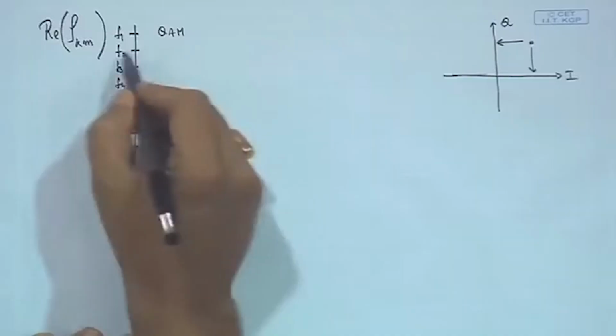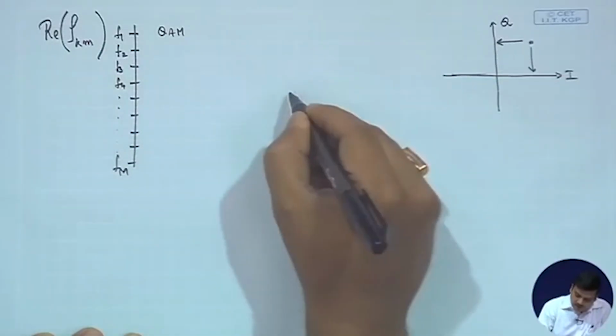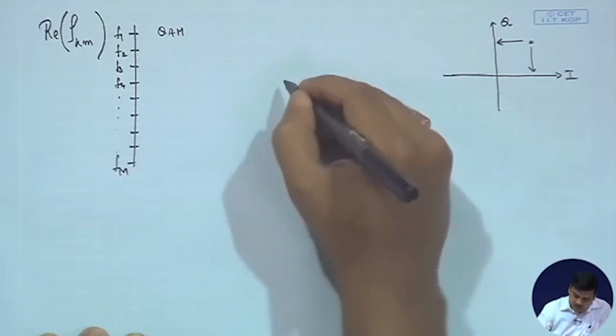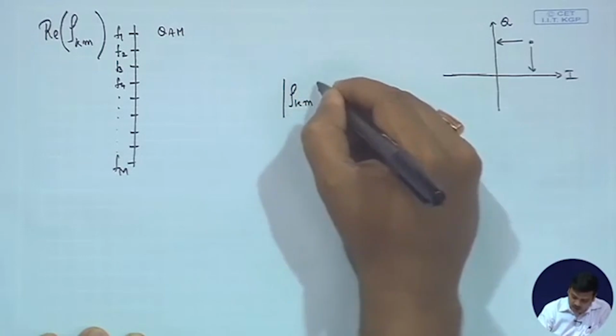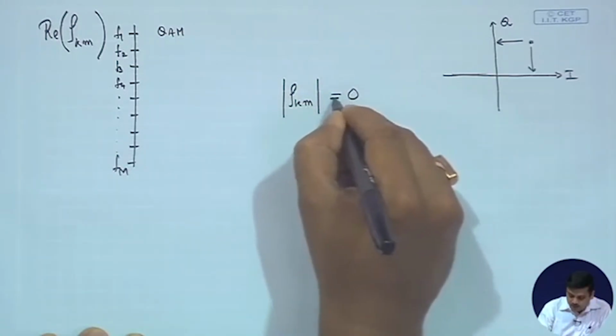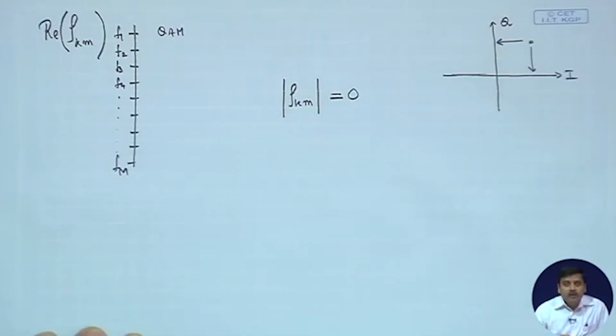So, when we are sending this and we are interested in rho km, what we should be interested in is when the absolute value of rho km goes to 0, right. Only then will we be able to decipher whether the signal is present in one of the components or not, and further decode how many bits were used in choosing a particular QAM constellation.